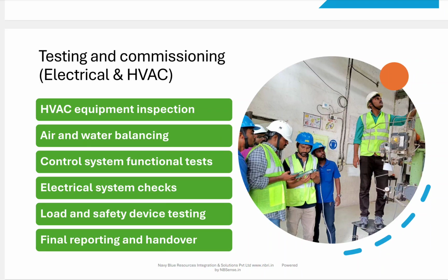As per design, how much you have installed or how much you are practicing there, that gap we need to identify as a third party. Then we suggest a snag list. Snag list means pending list. This is as per the design standard and you didn't do this as per the design, now you have to rectify it, then we will come and do a final commissioning. There are pre-commissioning, commissioning and post-commissioning, three to four stages. Then we have to summarize everything in the report.